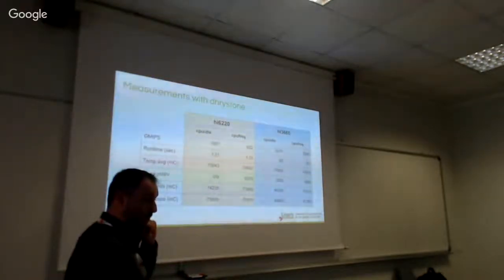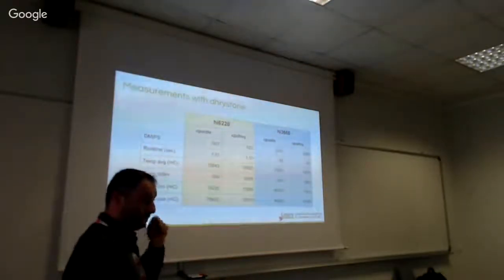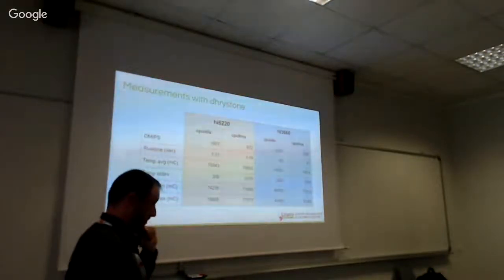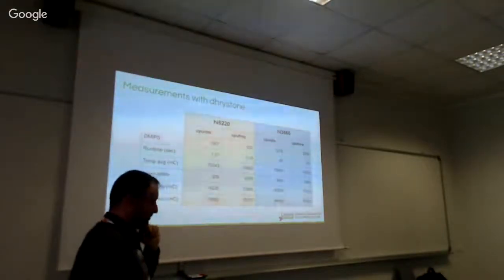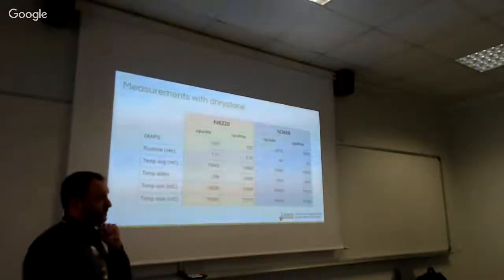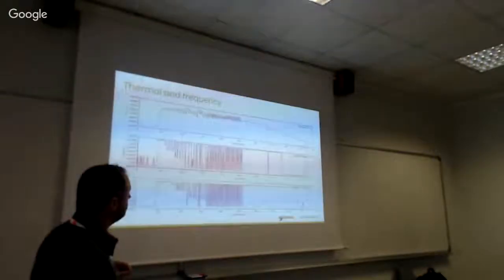Well, from a power perspective, it will be the same. Yeah, but you would get better throughput because you will actually be running some part of the time at the lower OPP, but the voltage is low, so you heat up less. So if you integrate over everything, you should get more throughput by just modulating how you use the OPPs instead of injecting idle where you force the whole system to stop. When you're running, you always pay the full price in energy for what you're doing, while if you modulate the two, then the time you spend at the lower OPP, you actually pay less for the work.